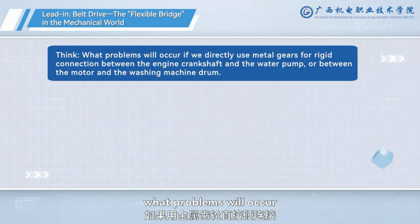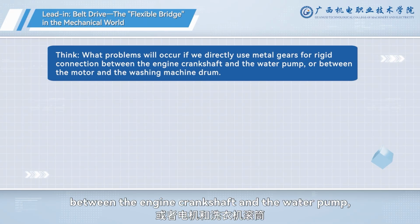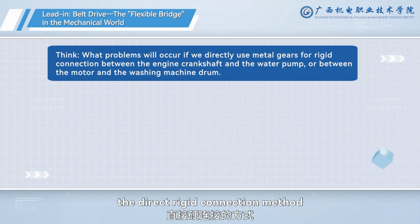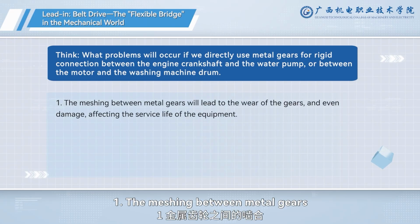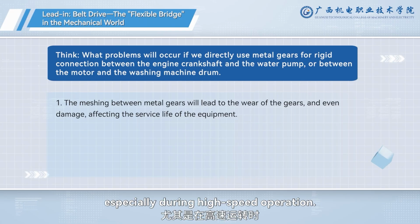Then let's think about what problems will occur if we directly use metal gears for rigid connection between the engine crankshaft and the water pump, or between the motor and the washing machine drum. First of all, the direct rigid connection method may lead to the following problems. 1. The meshing between metal gears may generate great impact and vibration, especially during high-speed operation.